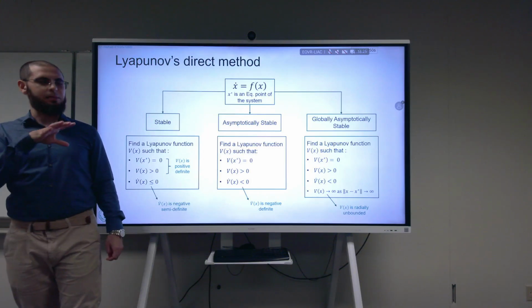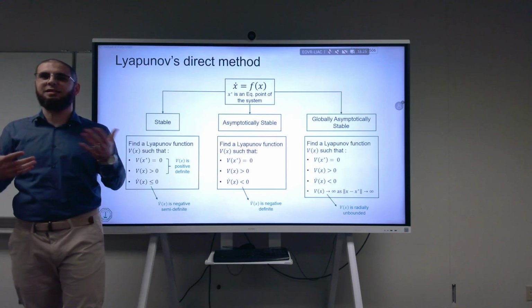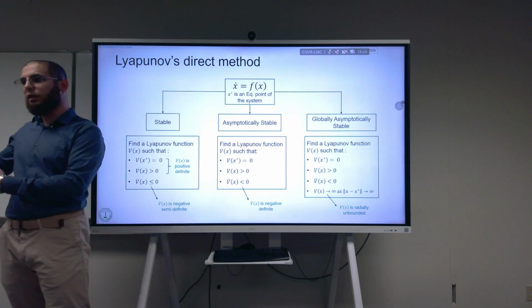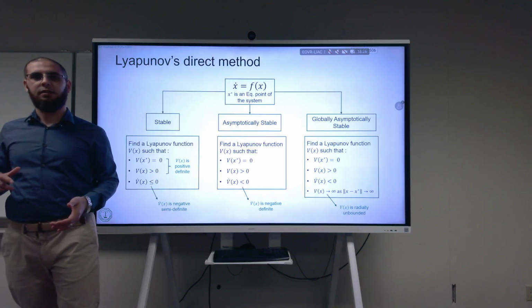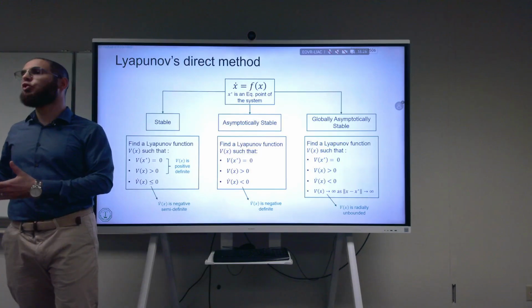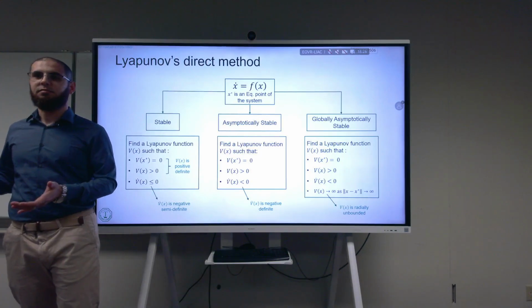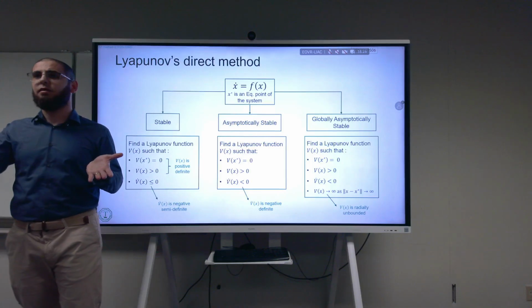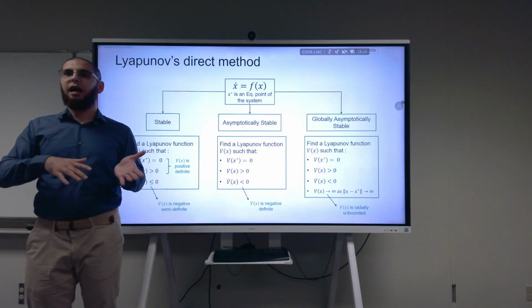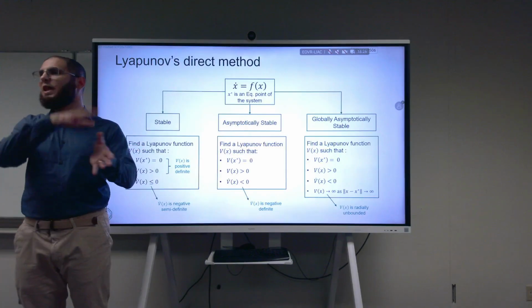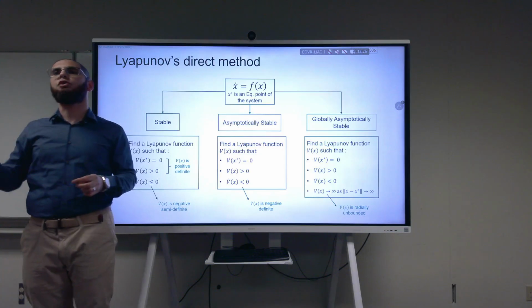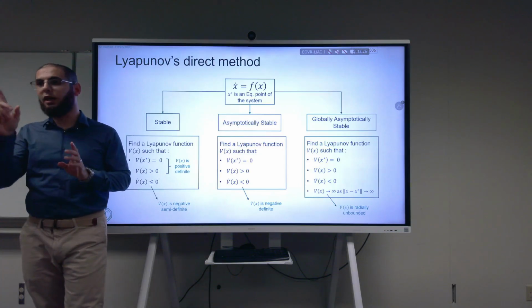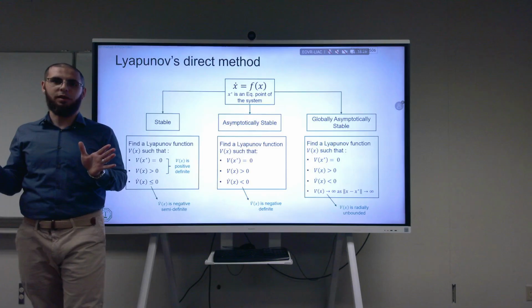And I mentioned something about when we're checking the stability, what else we're going to be doing along the way? Controller. Designing the controller, exactly. So if you're designing a controller, do you want to prove it's stable or unstable? Not only stable. Stable means that I start from some initial condition, and the error will keep on roaming. Asymptotically stable. Asymptotic stability is always the minimum requirement. Locally, local asymptotic stability is always the minimum requirement.